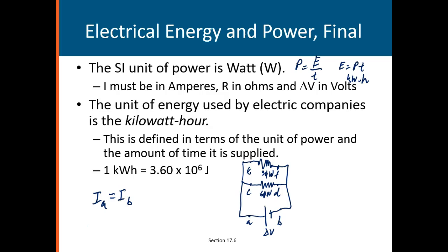If those were ohms, I would say you're absolutely right. But these are watts. Because guess what? The same voltage here is there and is there. Okay? And power, that's what the watt measures, is voltage times amps. Same voltage, greater power, greater current. So C and D are next.